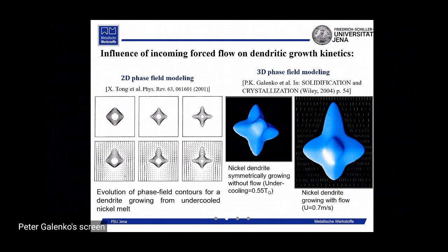And the second answer to why we have a developed branch takes into consideration the isotherms around the dendrite. Why? Because isotherms show us the direction of thermal gradient, right? So the much higher or warmer isotherm lies around the dendrite, and the much cooler isotherm lies behind the interface, and the gradient is directed from the cold to the warm part of this heat field, and in this direction crystal branches grow. So velocity is proportional to the temperature gradient, right?